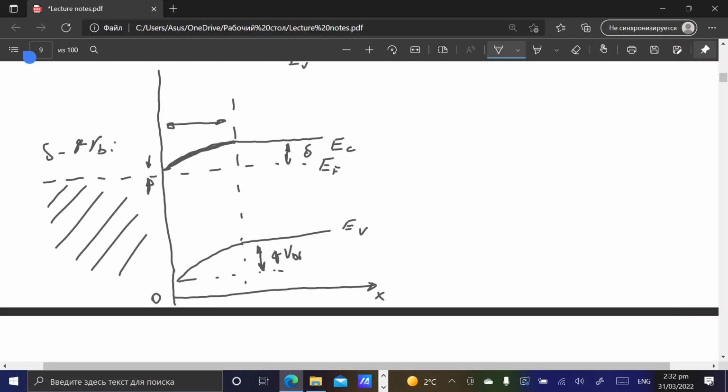That results in different polarities of space charges which are formed in semiconductor and metal, and depending on polarities, we get either upwards or downwards bending of bands in the semiconductor, which leads us to either a region depleted of majority charge carriers, high resistance and high external bias dependence of the resistance of this depletion region, or in the opposite case, we get increased concentration of free electrons, low resistance, and weak dependence on external bias.